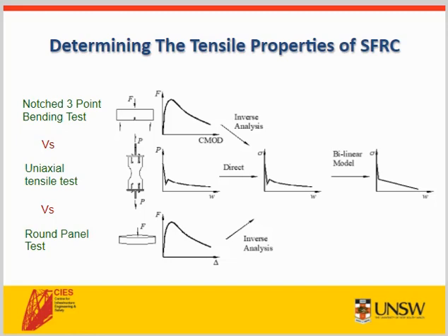The round panel test specimen is a relatively large specimen, which has a diameter of about 800 millimeters and is approximately 75 millimeters thick, and therefore is quite heavy and difficult to handle. But with the formation of 3 fracture lines, scatter in these tests is typically low, and hence characteristic values can be high. For the prism bending and round panel tests, some sort of mechanism is required to convert force displacement data to stress versus crack opening displacement.